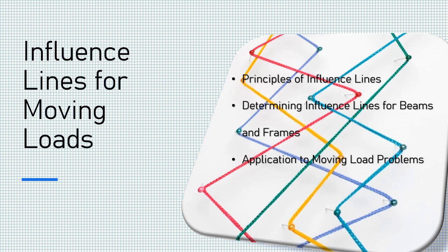8.4.1. Influence line for reactions. Consider a simply supported beam with 2 supports at each end. If a unit load moves across the beam, the reactions at the supports change. The influence line for a reaction at one of the supports can be obtained by placing the unit load at various points along the beam and calculating the reaction at that support.